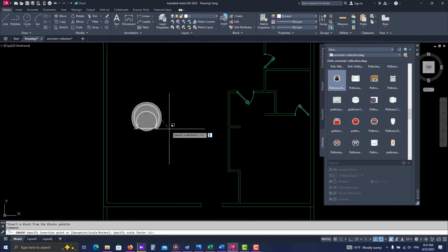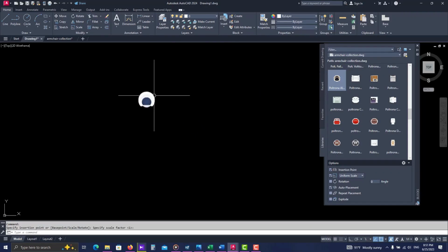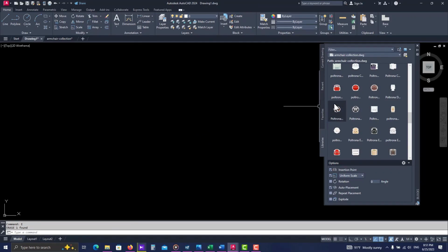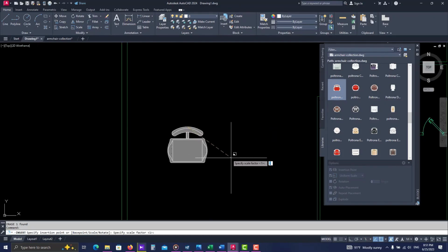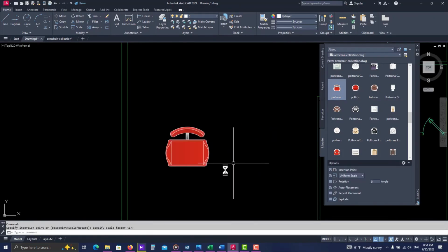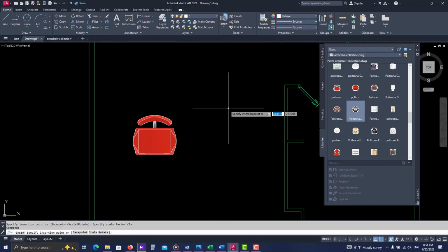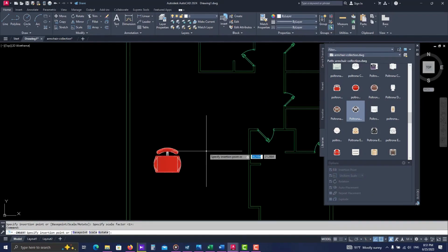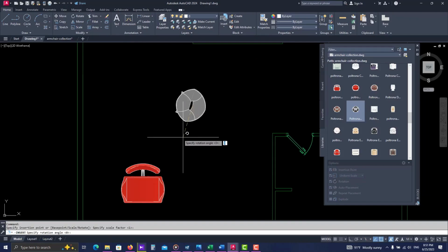After that, we can select and replace each of these blocks by click and drag like this. As you can see, we can define the scale by pressing down enter. Watch this. We can resize it easily. Again, I want to replace another furniture, another block. Watch this. And then we position it. And if we want to rotate it, we select it, then we check rotate, and after we click in the scene, we can rotate the block as well.